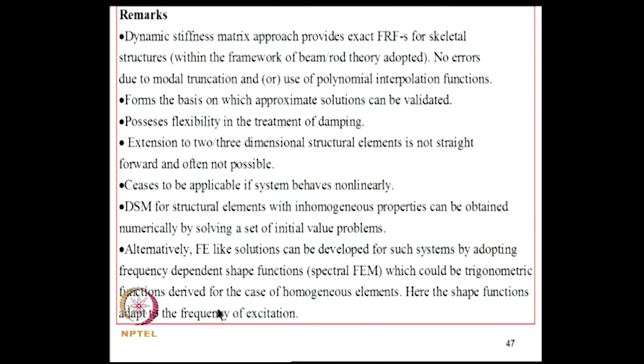These could also be trigonometric functions derived for the homogeneous elements, but the computations would become tedious. The advantage would be that the shape functions will adapt to the frequency of excitation. We need not refine the mesh if frequency increases.